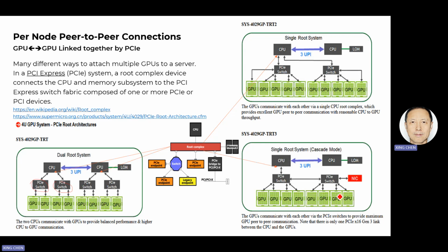But there is one point: if the GPUs have to communicate with each other by going through the PCIe switch and the PCIe link, there is a requirement that these PCIe switches and these GPUs have to be connected to a single root complex. So let's have a look at this one.